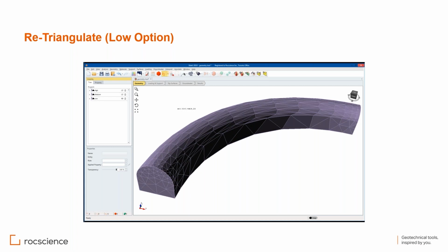So if this surface mesh is bad or too dense, it's going to affect your volumetric mesh, which is very important in the finite element analysis. But in the limit equilibrium analysis, as long as this one is fine enough that you are able to create a geometry, and your geometry is not problematic and represents your topography, for example, that's fine because it's limit equilibrium. It's not that complicated as long as you are able to create your geometry.